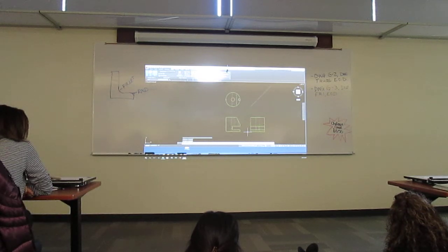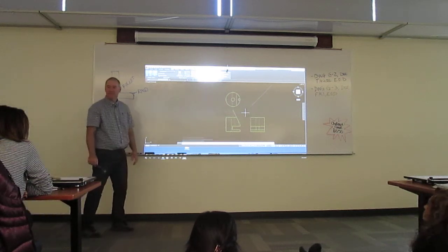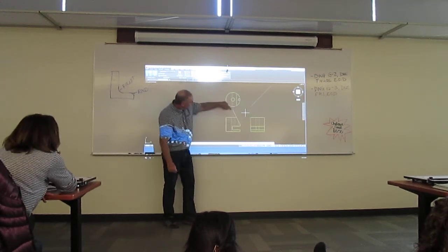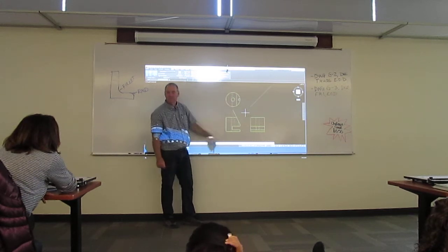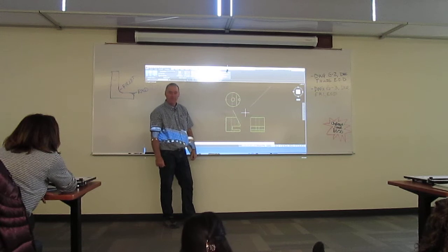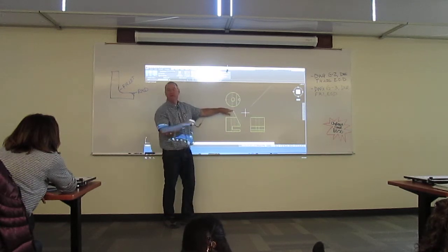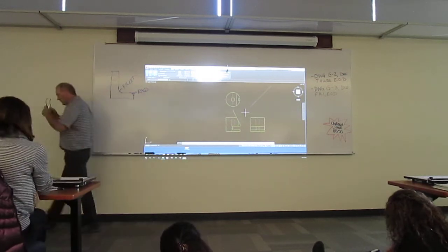Hey, I know it's not there, but what I'm going to do is I'm going to come up and take this center line and extend it up, and then take that plane and extend it to it. Because if that plane kept going on that angle, that's where it would hit. Right? I never changed the orientation. All I did was project them out. Now at this point, do I know these centers? I most certainly do. So I can now track along this line, get my center point, get my major radius, get my minor radius. And let me show you how I do that.